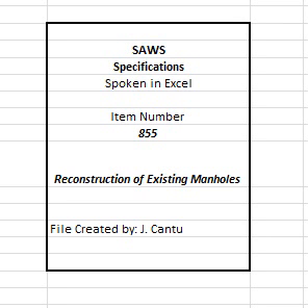C. D 638, Test Method for Tensile Properties of Plastics. D. D 648, Standard Test Method for Deflection Temperature of Plastics under Flexural Load in the Edgewise Position. E. D 790, Flexural Properties of Unreinforced and Reinforced Plastics and Electrical Insulating Materials. F. D 1238, Standard Test Method for Melt Flow Rates of Thermoplastics by Extrusion Plastometer. G. D 1505, Standard Test Method for Density of Plastics by the Density Gradient Technique. H. D 1693, Standard Test Method for Environmental Stress Cracking of Ethylene Plastics.